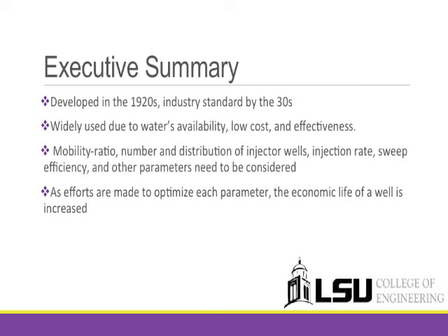Our goal is to look at these key factors and optimize a water flood design to add value to a mature field. This can be done by optimizing the injection rates and sweep efficiency, adding polymers to injection water, and maintaining the pressure control of the well. Overall, the entire purpose of applying secondary oil recovery methods to a well is to improve the profit margin of the well. With water flooding being one of the cheapest secondary oil recovery methods available, it can be applied to many different types of reservoirs.